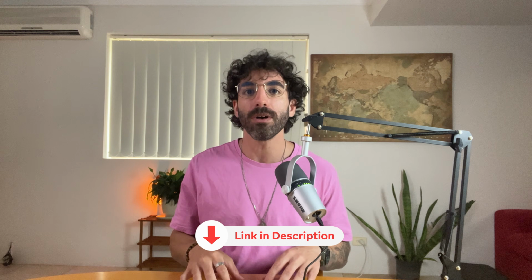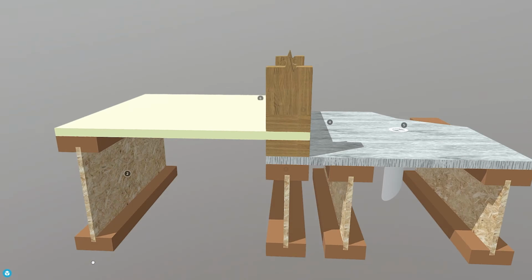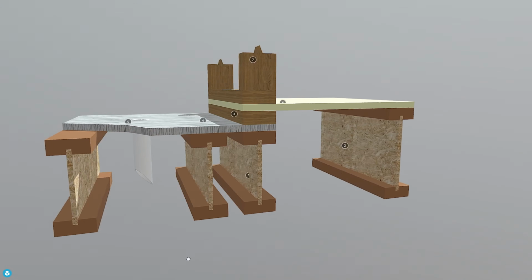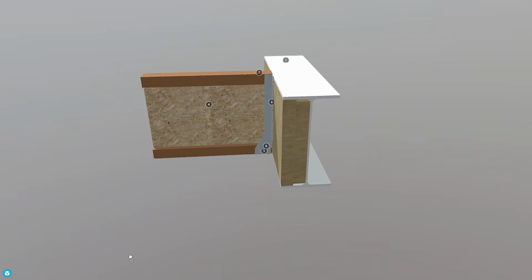Another great example we often discuss in our structural engineering community, that you can find a link in the description below, is how the nails and flooring help restrain floor joists, and how those floor joists then help restrain the floor beams. Each element helps stabilize the other, keeping the whole system in check. These restraints are considered effective if they prevent twisting of the cross-section and or lateral deflection of the critical flange.